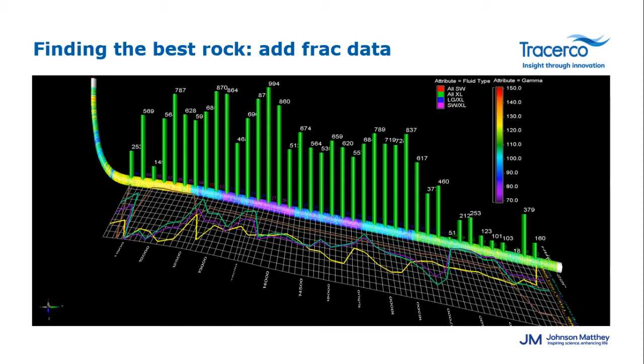The last bit of information available for this well was the completion stimulation data. Completions design and fluid systems can have a significant impact on the production as well as how the well cleans up over time. We have included the average breakdown pressures, the ISIP, treating pressures, and volumes placed using the different traced lines. There is a significant step change in the completions pressures measured during the completions of stages 1 through 10. Often, when looking at cleanup efficiency and production, further insight comes from the production over time rather than the cumulative production.